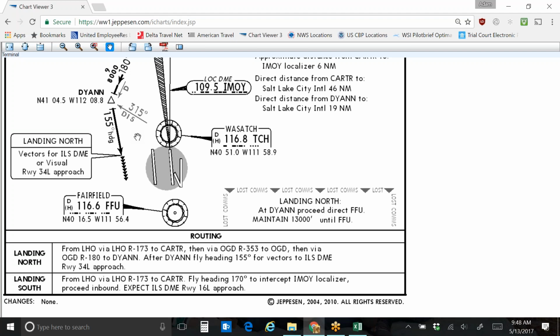It also will, depending on if there's a plane, say "Traffic," and there's a bunch of different parameters that it has to fall within. Like if the plane is within 1,000 feet of you and within 1 mile of you, then it knows it's going to alert you. It's going to say traffic, because even up in the RVSM airspace, your separation is always still 1,000 feet and 1 mile at a minimum, usually more than that, but always at least 1,000 feet. But the lateral separation is usually more than 1 mile. So anyway, it knows that that's a problem. Even in the most generous type of airspace, that's a problem.